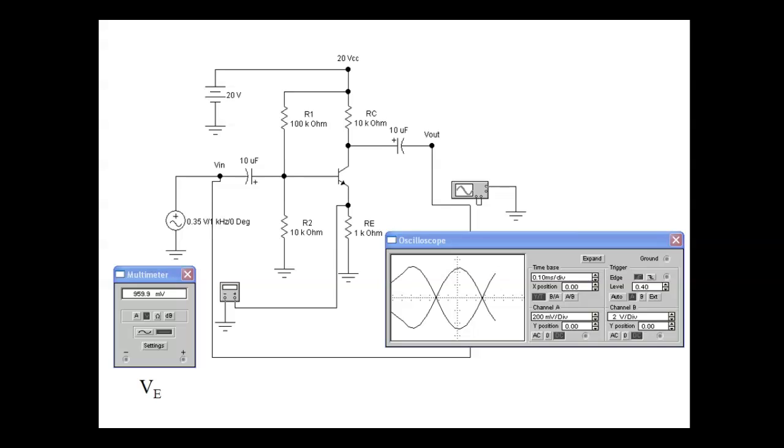Well, the transistor would be cut off, number one, because the base voltage is 0. But what would be the first place I would look at? R1. You're exactly right, because R1 and R2 are what's setting that voltage. So if this measures 0 volts, then the first place I would look is R1.